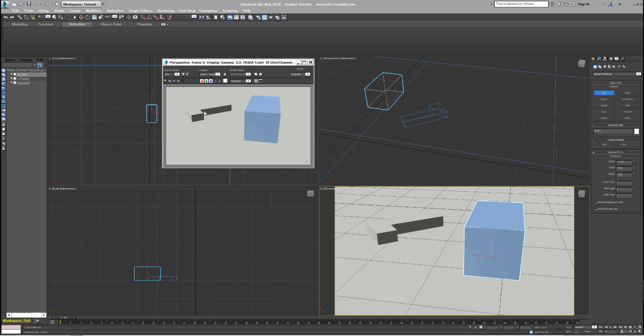So it's pretty useful because after that, it allows us to work with, if we're using an ART renderer or an Arnold renderer or a mental ray, we can work with effects like indirect light, soft shadows, color bleeding between surfaces, and we can suggest a realism that's really not attainable with scanline. So that's really helpful. So this demo today, we're going to work a little bit with scanline and working with sort of a ray tracing with scanline to see how light's transferred that way, but we're primarily going to be working with a physically based lighting renderer.